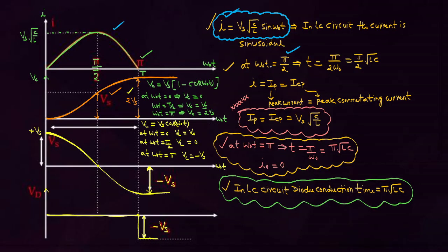We may expect either angle or time. They will ask the angle or they will ask the time for any competitive exam. If they ask the angle, at 90 degrees the current is maximum. If they ask the time, at pi by 2 root LC, the current is maximum.